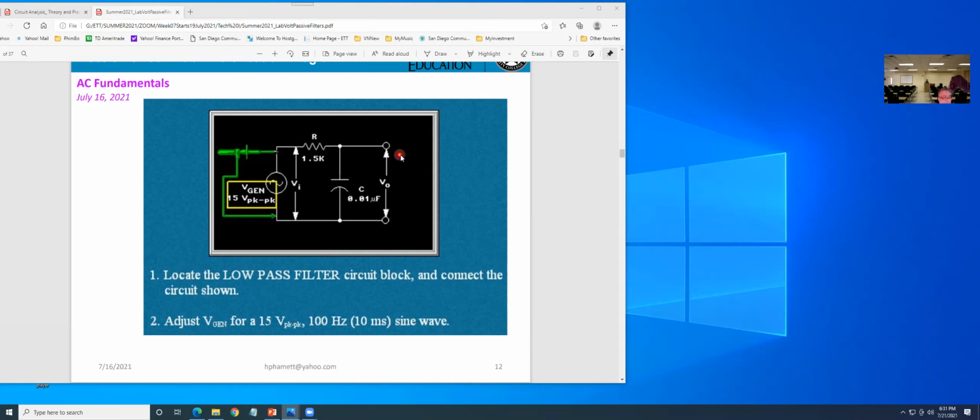How can you do? Suppose I tell the student, you have to do what? I cannot just say in general, you take your scope channel 2. Just disconnect your probe and then connect it at the generator to see if your cable is working. And if it's working, okay, now I agree. So in this case, we don't know if the circuit has a problem or your scope channel 2 has a problem. So we have to isolate one by one.